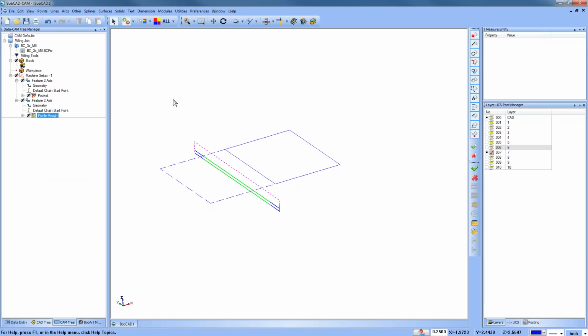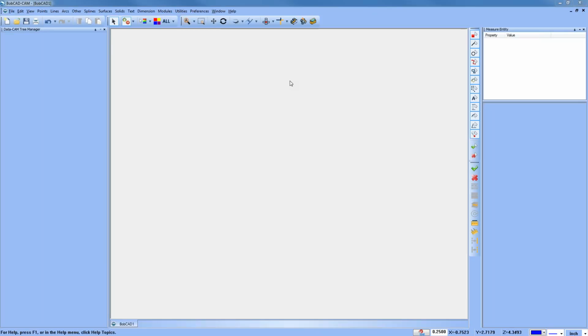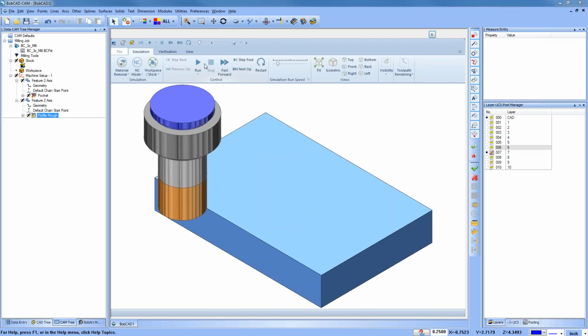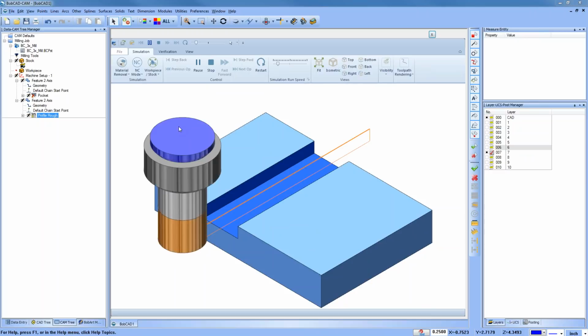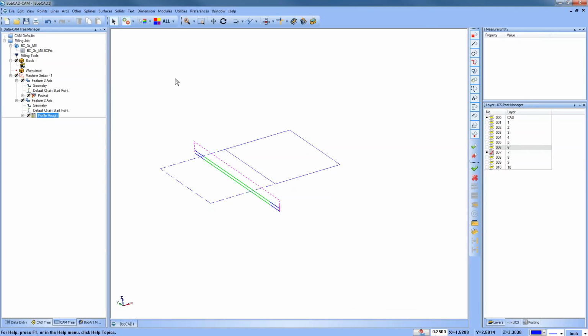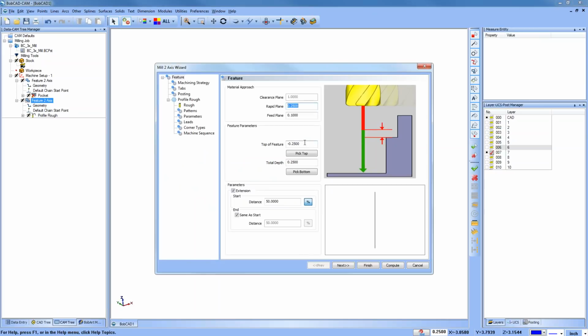And what you may want it to do is to actually machine quite a bit more. So let's run this through a simulation. We'll see how this is going to take 2 passes here. Pretty aggressive, but really we want to remove all of this material as well. And this is another example of where you can use your side roughing. So we'll go 0, 1/4 inch.